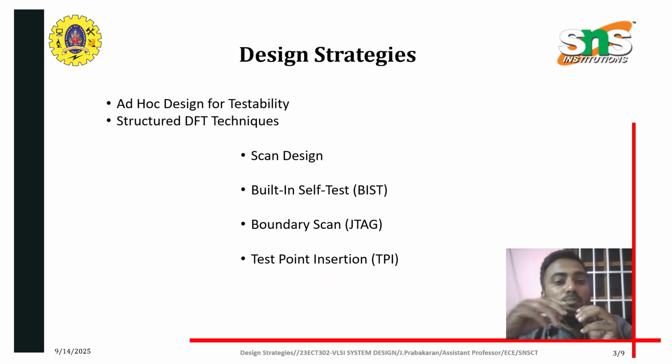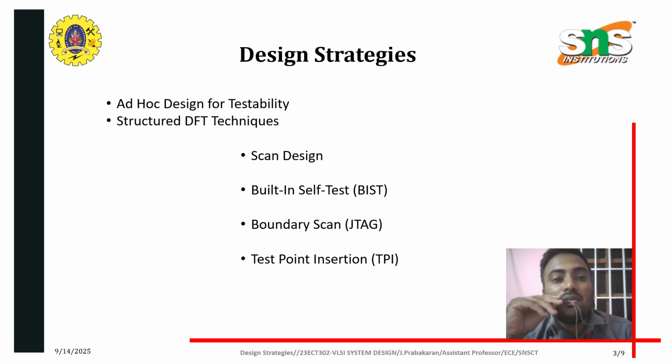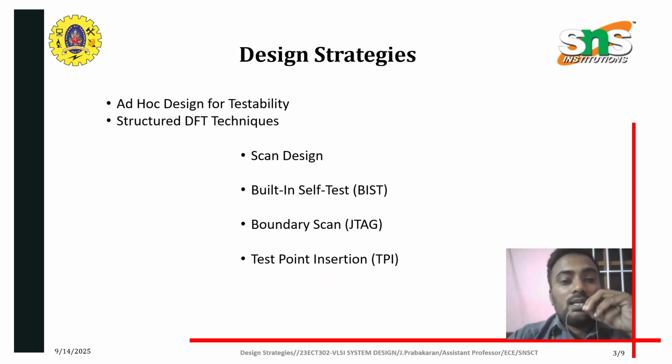Next one is built-in self-test. Already we have discussed that testing the circuit itself using on-chip behavior is called built-in self-test. The test pattern generator, response analyzer, and BIST controller are the components of this built-in self-test. And next one is boundary scan, followed by test point insertion.